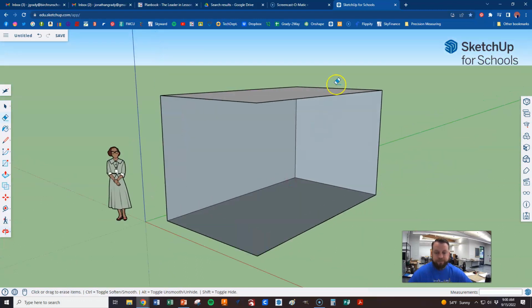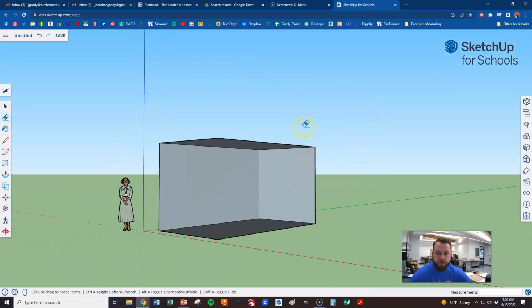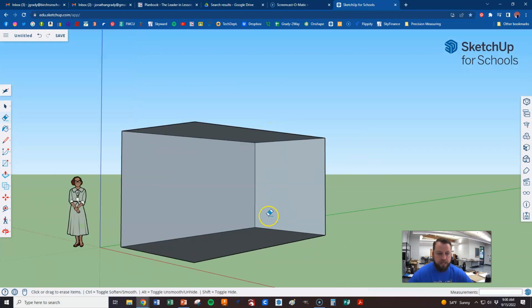All right. And now going from here, we're going to introduce a new tool, okay? And it's called the tape measure tool. What the tape measure tool does is it creates guidelines that can be really easily deleted later on, but give us a nice accurate way to make those guidelines so that we can draw with them. So if you hit T on your keyboard, it's going to take you to this tool right here. So I just hit T, and it highlights on this tape measure.